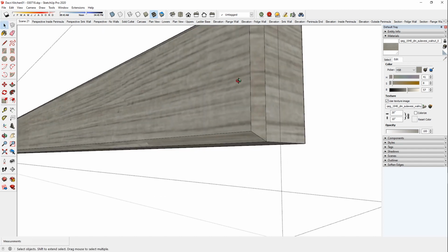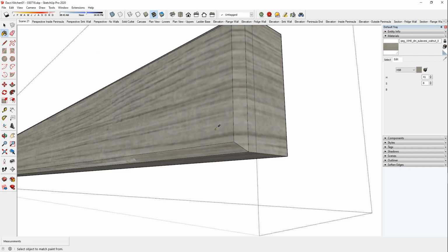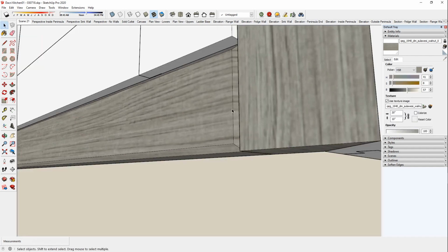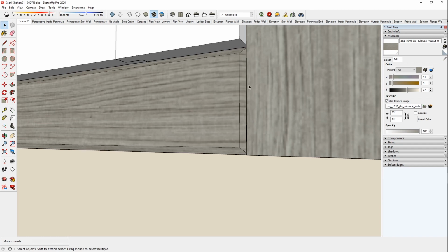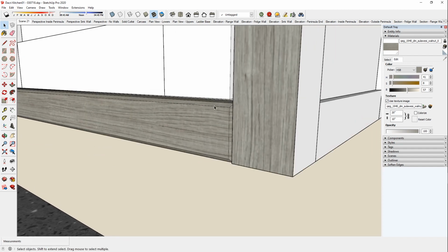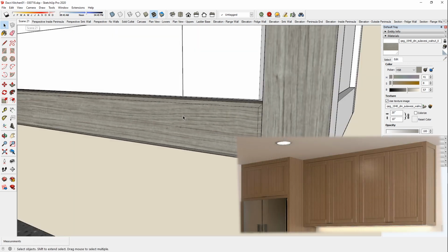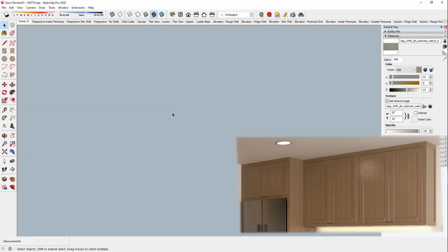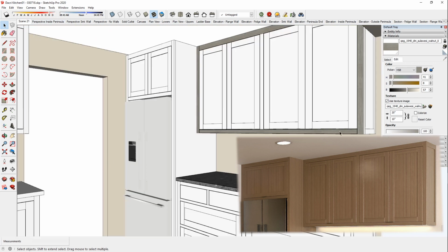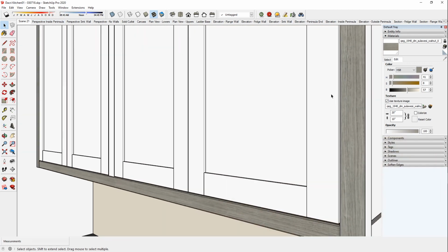If you bevel the edges before applying the texture, you will have to go in there and manually paint every single beveled edge, which will not be fun. So quickest workflow is to paint it first and then bevel the edges. The beveled edges, the mapping on them might not be that critical because when they change the angle in the view, the lighting changes on there, and the mapping, unless very close up like this, will not really be noticeable. But as you're further away, you can definitely see when the texture is either horizontal or vertical, and so that's critical to get on the major faces. So now if I want to use a vertical texture for this, let's select all these instances.